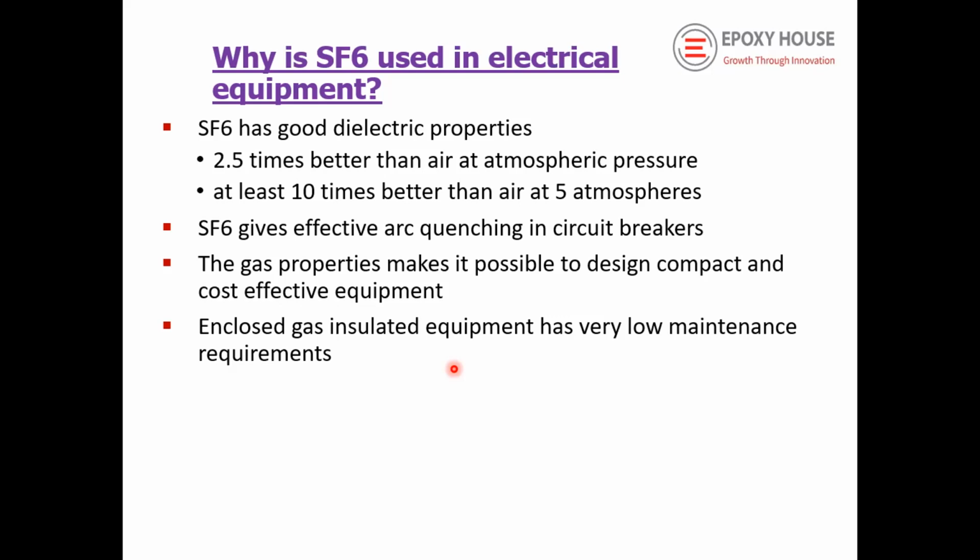The newer gases that have been found have very good dielectric properties, but their temperature requirements are not good. So they have a limitation and can be used only in lower percentages, because the few gases found with better electrical properties have limited temperature application. That's why they have to be used in a lower concentration, like 15%, 20%. The remaining will be carbon dioxide or nitrogen. So people are trying different compositions. Yes, it is in service now.